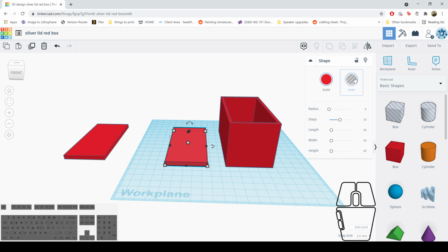And this over here is going to become our insert. So make sure this is changed to whole. We're going to bring up the ruler again, and we're just going to change a couple of things. We are going to change this 46.50 to 47. And we're going to change the 4.5 to an even 5. And that's it. You can dismiss the ruler.